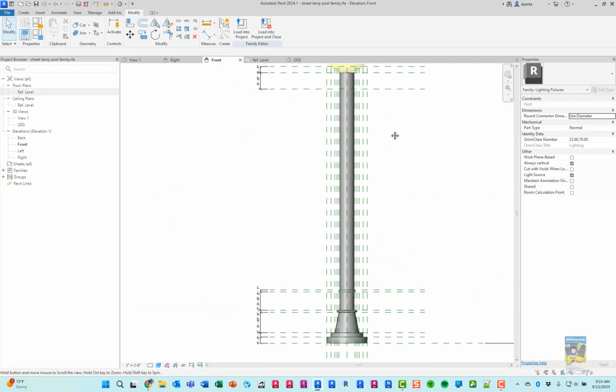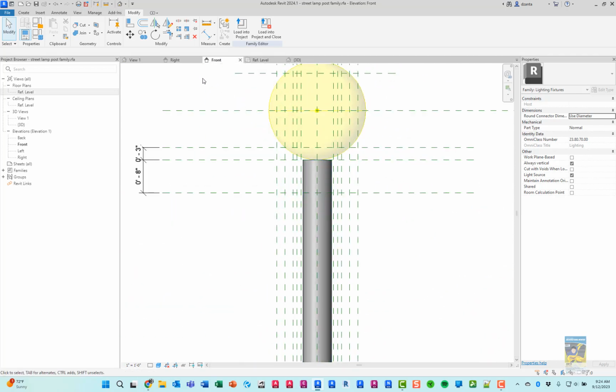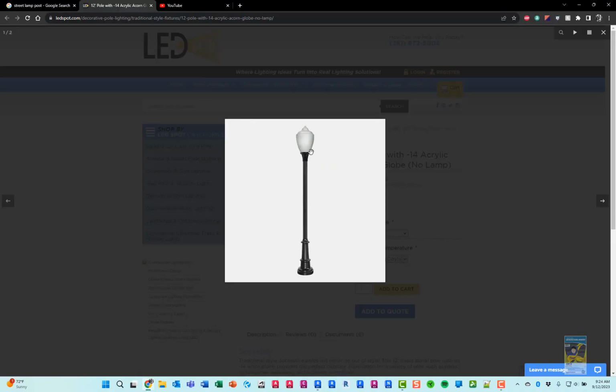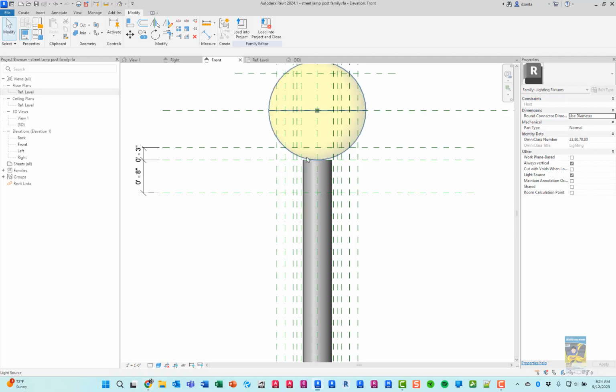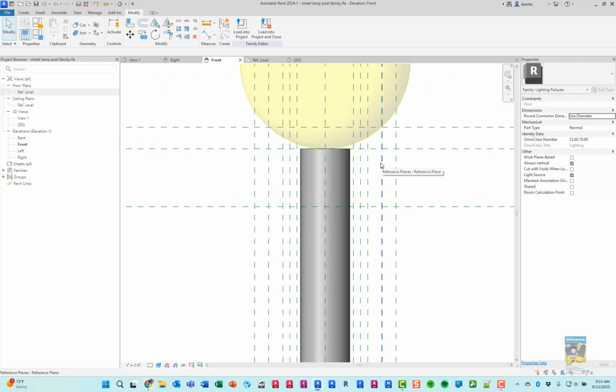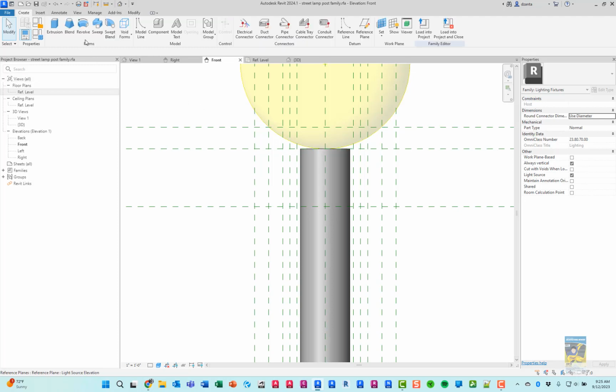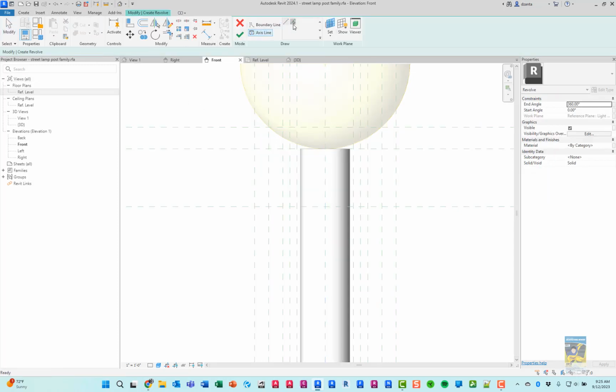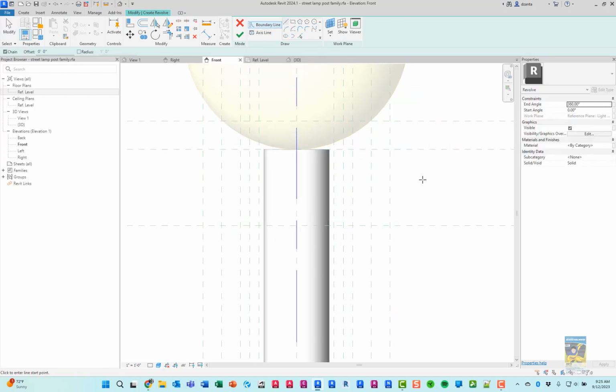We need to work on this top part here. So same kind of understanding. This time I'm going to do a revolve because this is kind of a unique little shape here. And we know we have a lot of reference planes to work with to create an interesting sketch, a revolve sketch. So I'm going to say create revolve axis line, picking the boundary line. So now I'm going to sketch a neat looking design. So I'll go here to here.